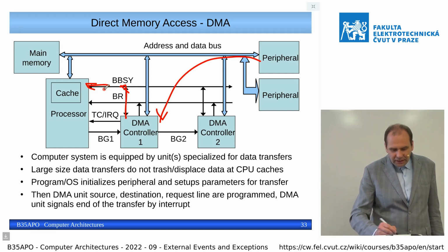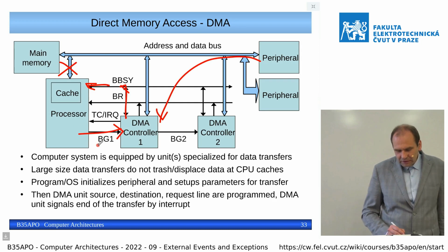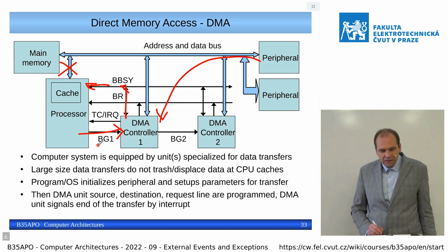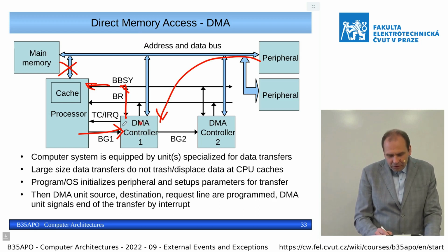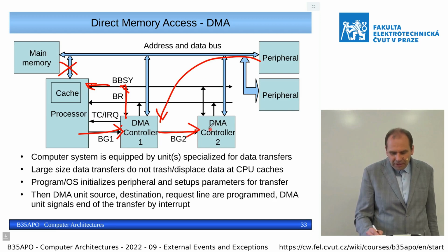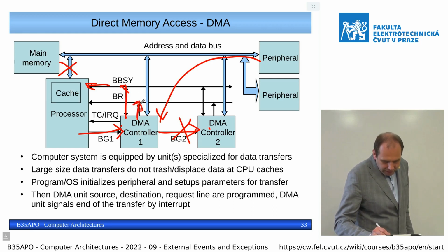Processor finishes the instruction, responds that it disconnects from the bus, and informs that it grants the controller access to the memory. If this controller doesn't need it, this is the so-called daisy chain setup in this example, then it can pass the possibility to connect, move the data and control the bus to another controller. But if this one wants to reuse it, it says okay, bus request, and this way it gets information.